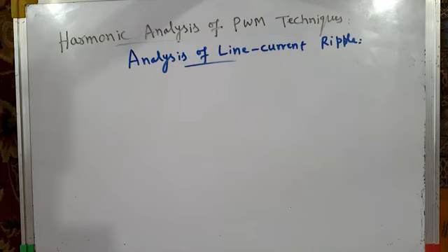And we have also discussed how this space vector PWM technique can be implemented using triangle comparison by generating a proper common mode signal and adding that common mode signal with 3 sinusoidal modulating waves. We have also studied space vector based continual clamp PWM, split clamp PWM, 60-degree clamp PWM, which is a special case of continual clamp PWM, 30-degree clamp PWM, which is also a special case of split clamp PWM. And finally, in last couple of lectures, we have been discussing about advanced bus clamping techniques like advanced continual clamp PWM, advanced split clamp PWM techniques using double switching sequence PWM.